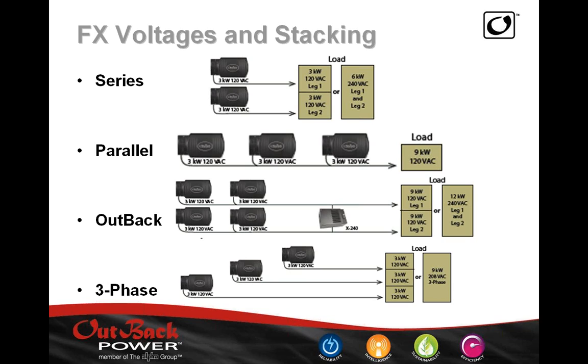Now, the difference between an off-grid inverter and a grid interactive inverter is that the grid interactive inverters can really only be stacked in series here or in 3-phase. We're going to be coming out with a new unit, a new hub that overcomes this issue, but for now, any system that is grid interactive can only have 1 inverter per phase. So we couldn't do parallel, and we couldn't do series.